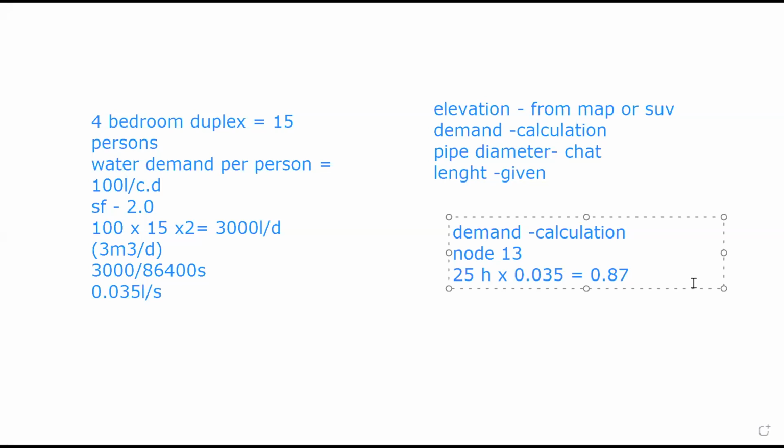So let us assume that the opposite plots will also be built in the future. Therefore, the number of houses connected to node 6 will now be 8. I can count 1, 2, 3, 4, but if I mirror it, if I assume that next year the landlord of these lands will get money and build their own house, I'll project that. That is part of what engineering is. So when I project that, it means I'm designing for 8.